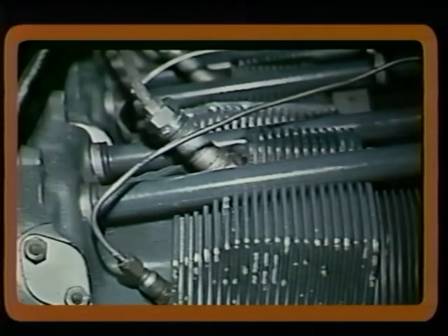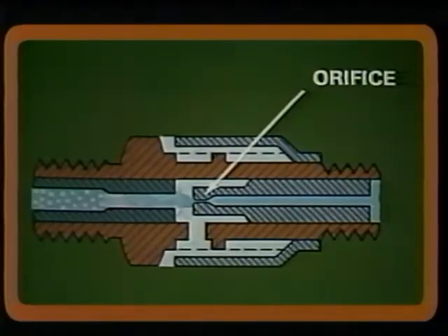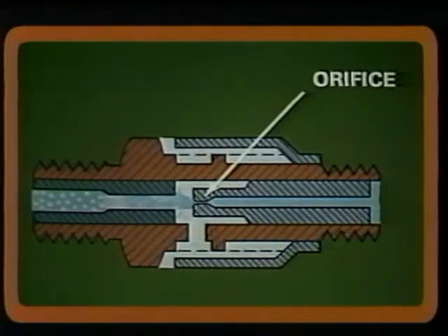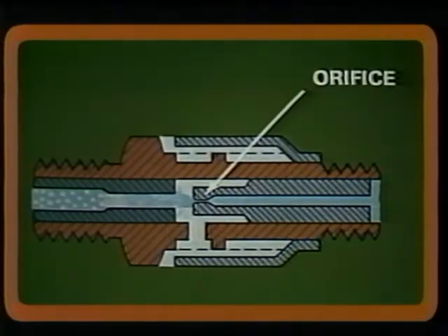These stainless steel lines of nearly the same length connect the distributor valve to the individual injection nozzles installed on the cylinder. The nozzles used in a continuous flow fuel injection system are the air bleed type. Now, this means the fuel flows from the distributor valve in a continuous flow and passes through a metering orifice in the nozzle.